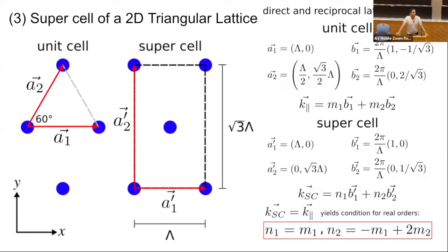In principle, I guess we could support that. We don't right now. Right now, we support localized waveguide modes. And the backend for that is using MPB as a mode solver. And then there's this diffracted plane wave, which is the non-localized. But yeah, that's certainly a feature that we can add. Basically, you'd have to implement it yourself right now. Yes. It's just another mode overlap.